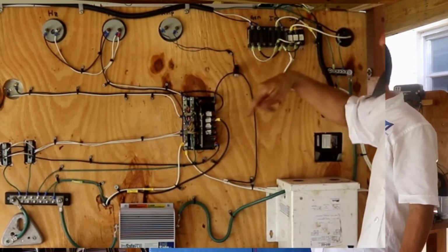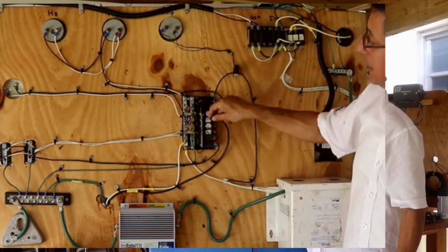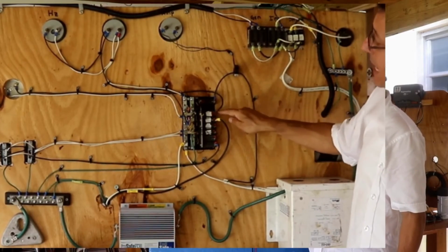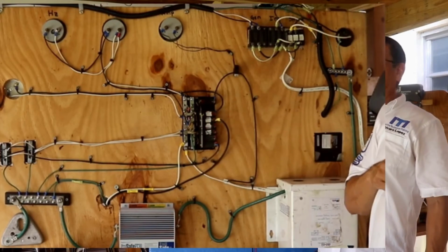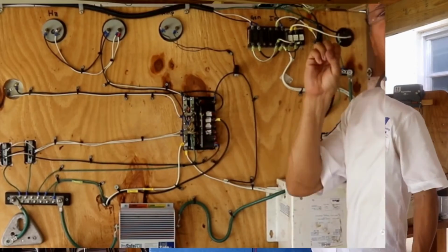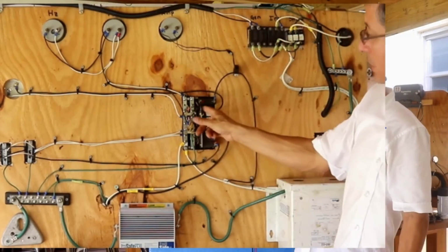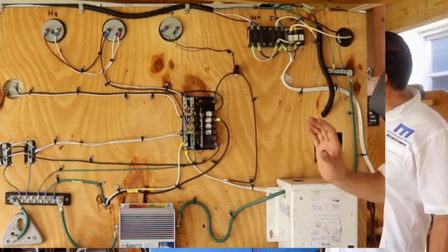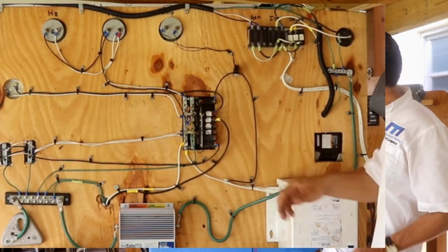Now we are going to turn the board and check the connection. The LEDs should be connected in the output of the breakers, not in the hotline at the input, because if you connect here, the LEDs are on all the time. That's not good. Okay, this is the procedure to do the wiring on the breakers.